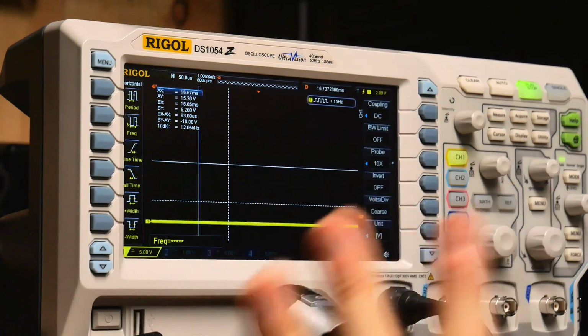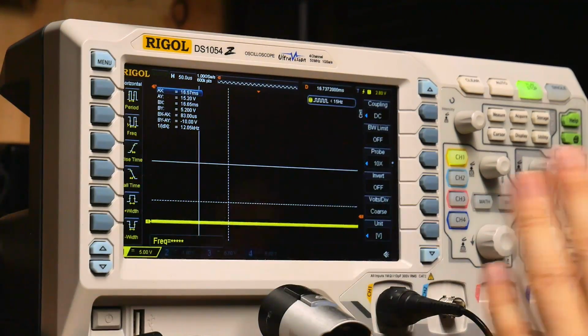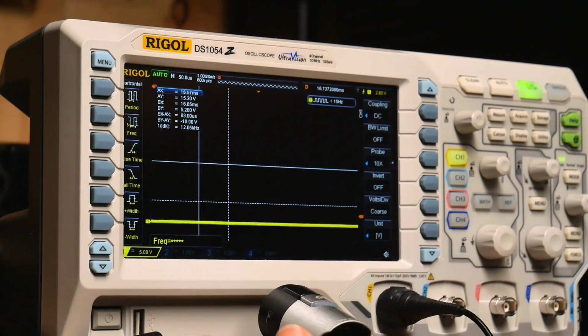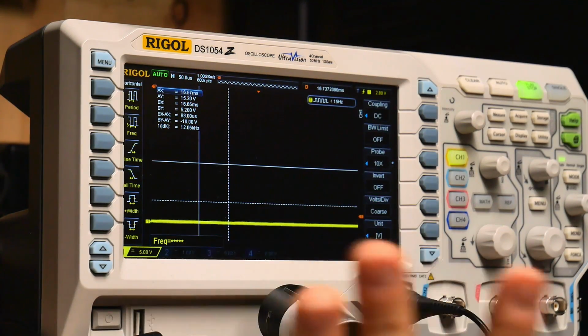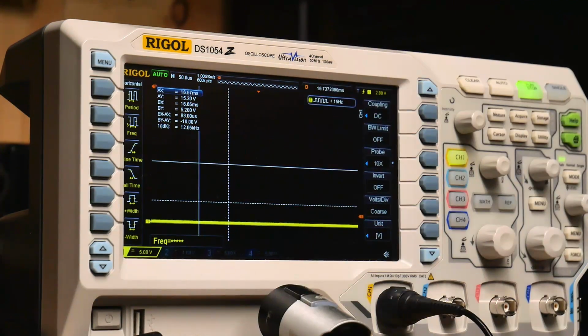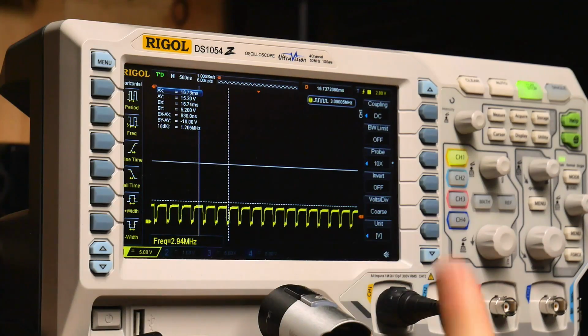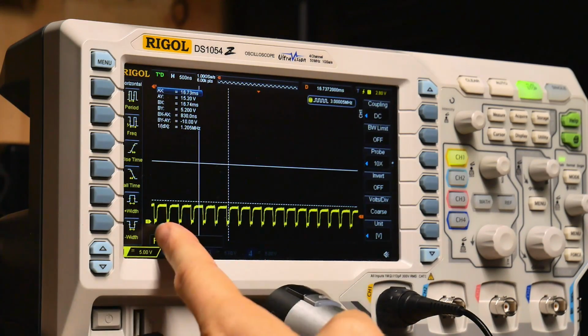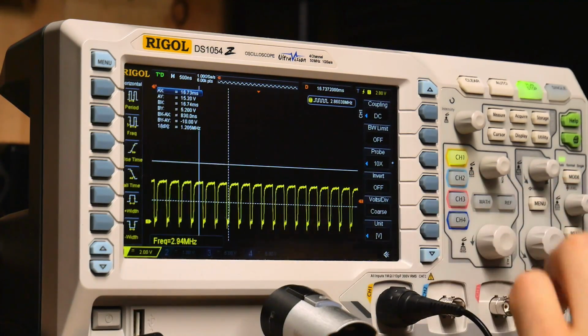Okay, so here's the oscilloscope. Sorry, I don't have 2 cameras set up, so you're just going to see what I'm probing here. So I'm going to check the 2 TTL clocks, then the 4 12-volt clocks, and then the 2 TTL clocks. I'm going to go around the pins, and let's start. All right, there's the first TTL clock. Now it's 5 volts per division. Let's turn this up so you guys can see a little bit better.